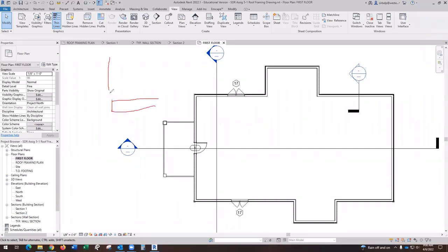I'm going to do a column. And the column probably shouldn't hang out over the edge of the slab. I think one of these I drew hung out over the edge of the slab, but ideally the column should come up to the edge of the slab. And then that beam should probably be centered on that column because that's where the structural piece would be. Does that make sense? Yeah.